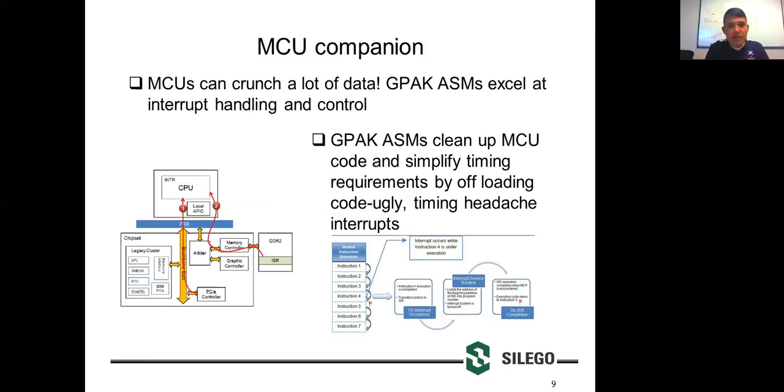So in the microcontroller world, we have things we call interrupt service routines. You have to detect the interrupt, then run over to the specific code associated with the interrupt, run that code, then jump back to your main code, and all this kind of stuff goes on. And then you have multiple interrupts happening at the same time, and you have to make sure that all of your code plays nicely with each other. It's a nightmare. It is extremely difficult, and that's why firmware engineers make the big bucks. It's because they have to make sure that under no condition, with all these interrupts happening in random orders, their microcontroller firmware code stays healthy, knows exactly what to do, and always goes to a known condition and never runs into problems like infinite for loops. And all of this needs to be timed out in real time to make sure that your system not only stays crashless, but also meets the requirements of the system to be safe for the customer's usage.